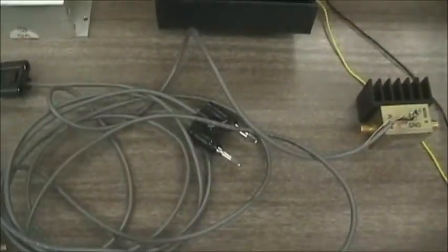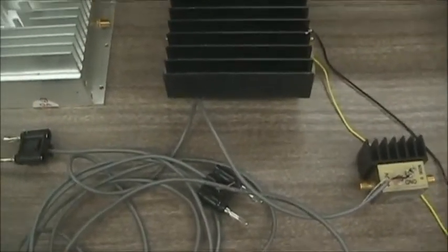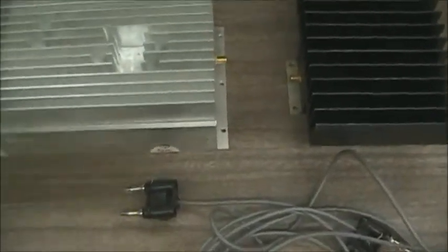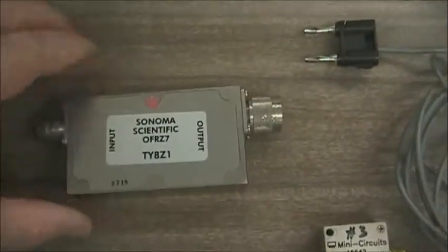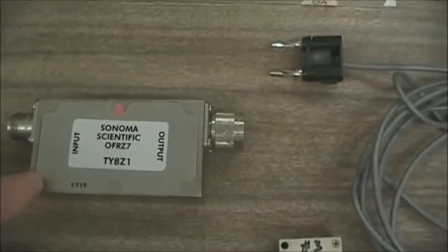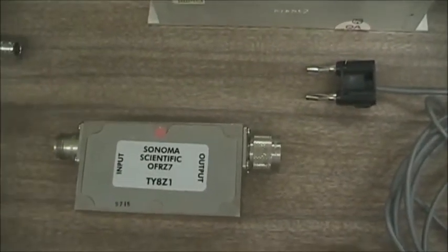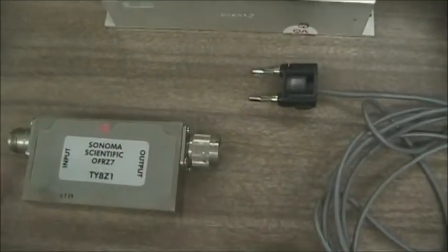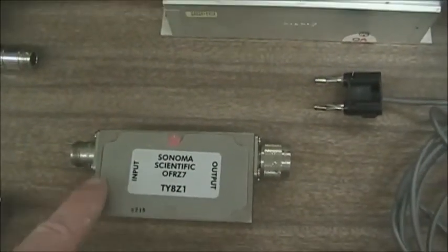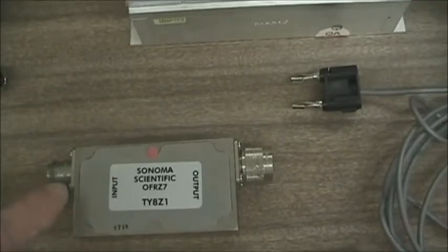Now, these three, attenuators, filters, and amplifiers, aren't the only two-port devices. We sometimes use devices like this, which is an isolator. Okay, very unique device used in RF. If I want a signal to go one way, then I can use an isolator, which is specialized.